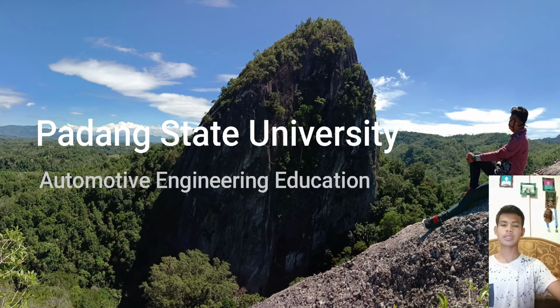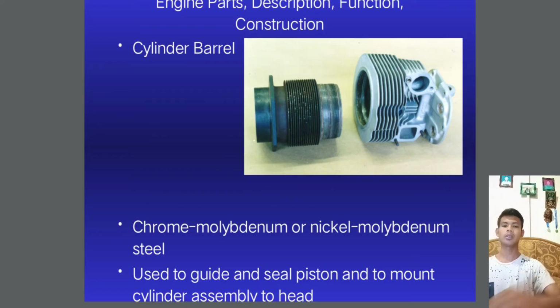Now we will discuss engine parts, description, function, and construction. Cylinder barrel: chrome molybdenum or nickel molybdenum steel, used to guide the piston and to mount the cylinder assembly to the head. The barrel threads into the head to form the cylinder assembly.